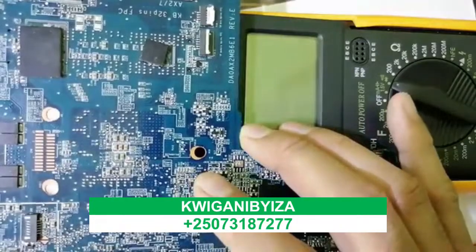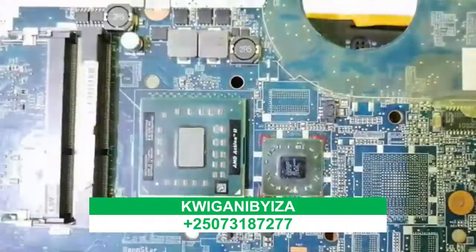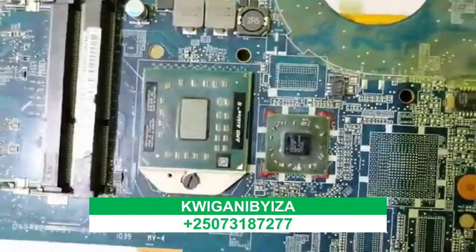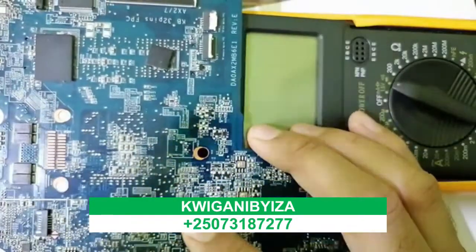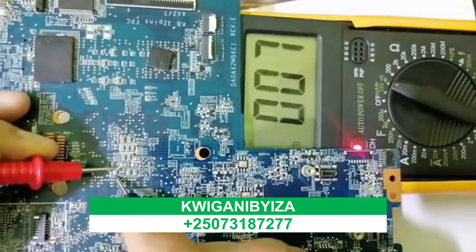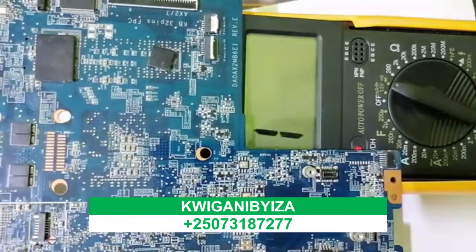If we put back the processor, as you can see, the processor is installed. So let's check again, just to make sure. One probe here, the other probe here, as you can see in the multimeter. We get a low reading. This is not a short.